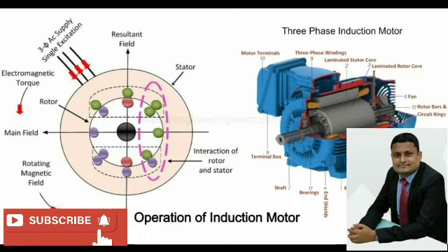The 3 phases of the stator winding can be connected either as star or delta, depending on the starting method employed. Squirrel cage induction motors normally use a star delta starter, based on the rating of the motor and the requirement of the customer. Accordingly we are using that. 6 leads are taken out of the motor through the terminal box. If you talk about slip ring induction motors, they are started by a rotor resistance starter. The stator can be permanently connected as star or delta as desired.